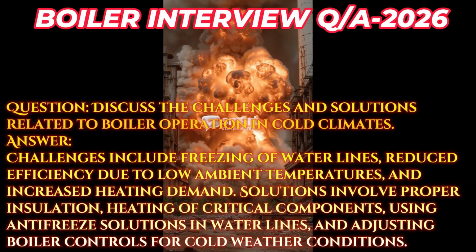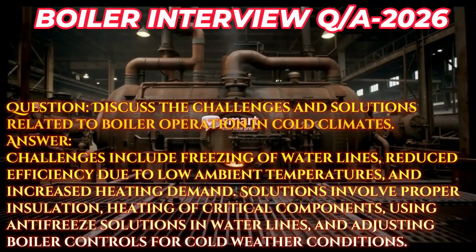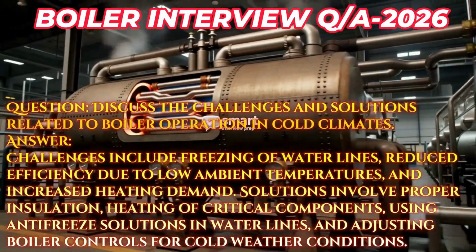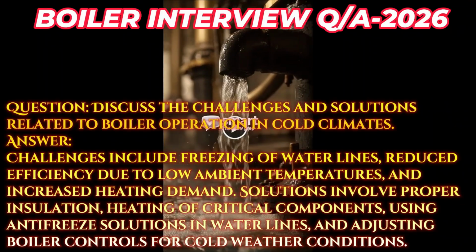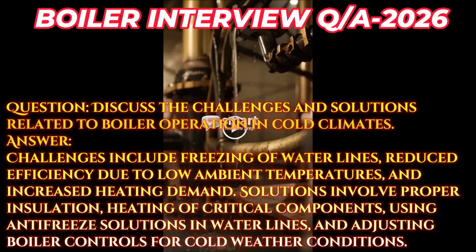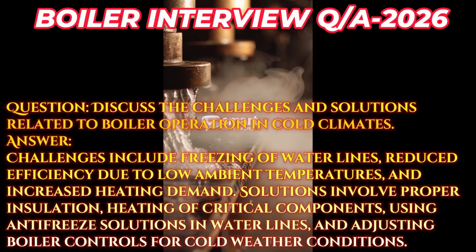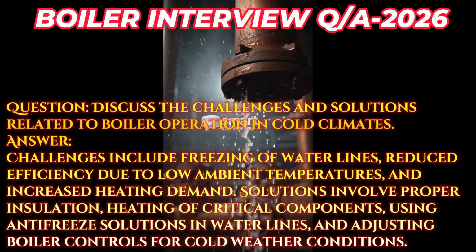Question: discuss the challenges and solutions related to boiler operation in cold climates. Answer: challenges include freezing of water lines, reduced efficiency due to low ambient temperatures, and increased heating demand. Solutions involve proper insulation, heating of critical components, using antifreeze solutions in water lines, and adjusting boiler controls for cold weather conditions.